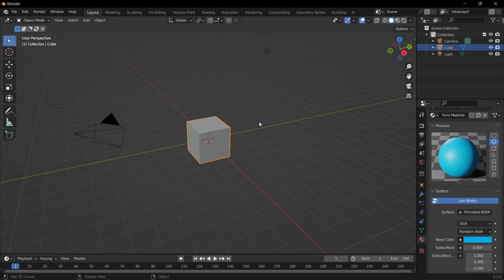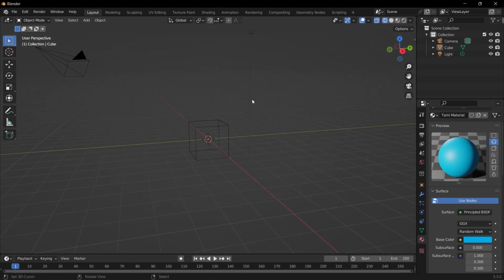In Blender, there are 4 different shader modes. The first one is the one you see here, which is the solid shading mode. This defaults all of the objects to gray, and there's no light interactions or any render properties that you've enabled. If we go to the top here, you can see the 4 different options, which are laid out here. So the first one is X-ray mode. As you can see, all of our faces are invisible, and we have more of a skeleton of our objects.